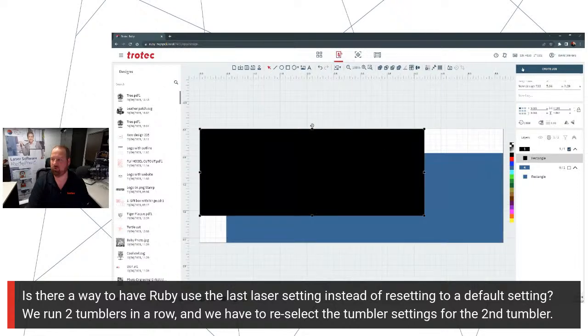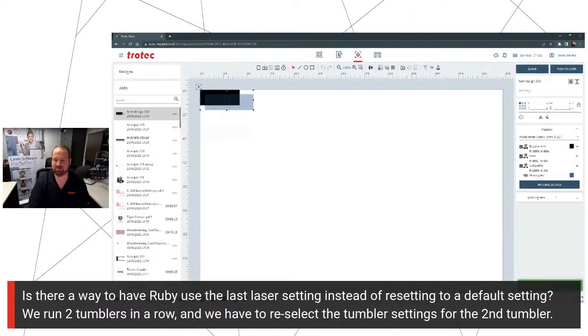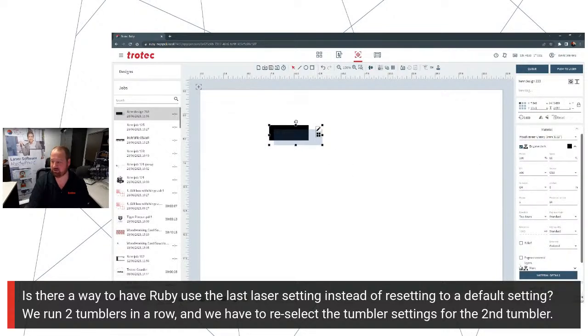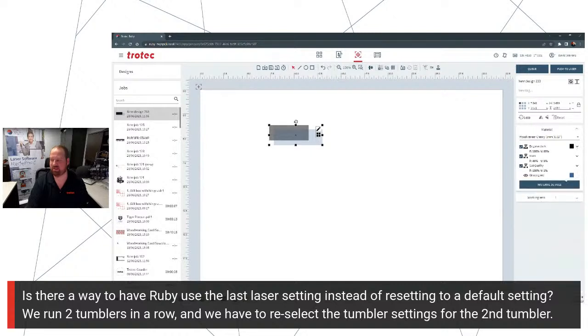So if I were to create a job and send this to the laser right now, if I have the overlap button turned on, which the engrave covered here, it'll engrave both of those files and give me the parameters and engrave both parameters that are assigned. Right now, I don't have an assigned file for this, but it will allow you to do that.